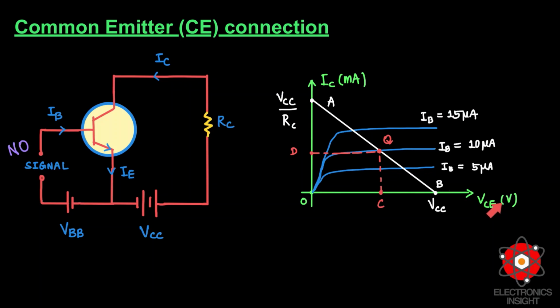And one of those methods which can be used is to plot the output characteristics to determine the output collector current at any desired collector to emitter voltage. However, a more convenient method, which is known as the load line method, can be used to solve any such problems related to the output characteristics analysis of common emitter or any such configurations of NPN transistor.